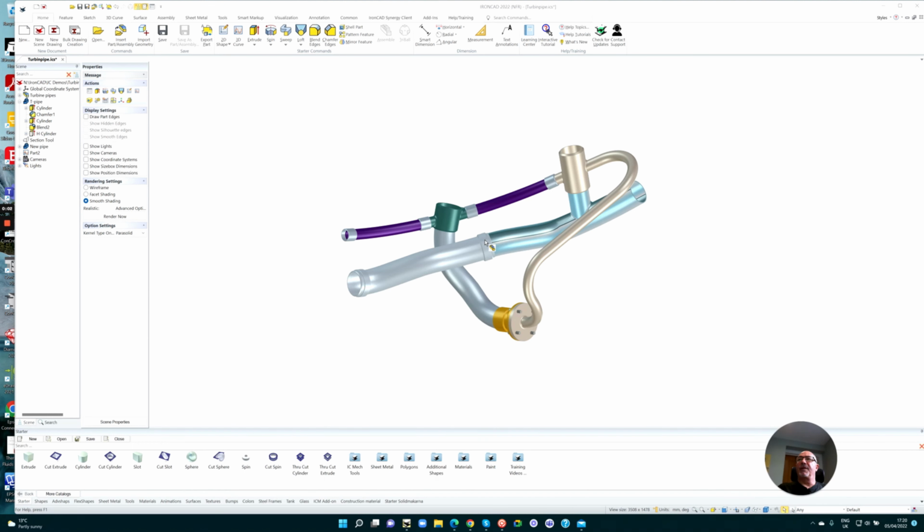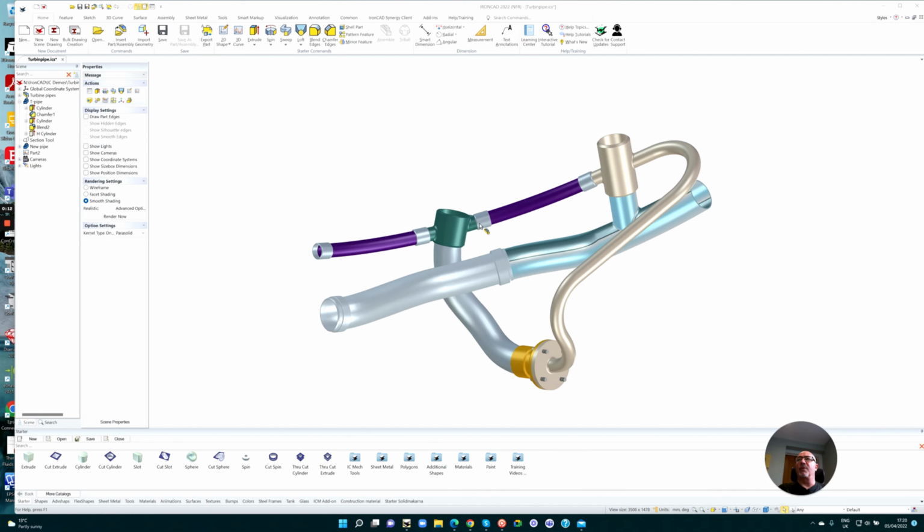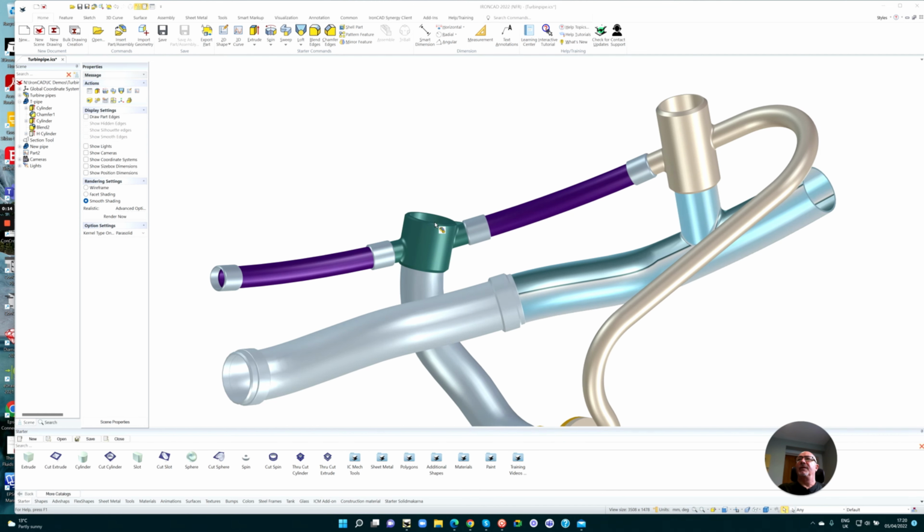This is part 3 of the single scene environment, where I'm showing you how easy it is to create additional parts to an assembly by using the existing geometry. In this case, what we're going to do is connect a part to that TP set and then sweep it out to some form of manifold above there.